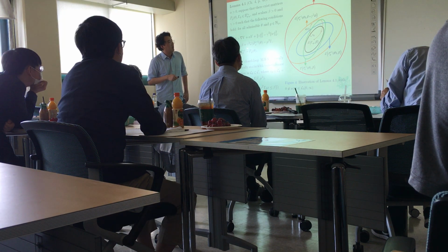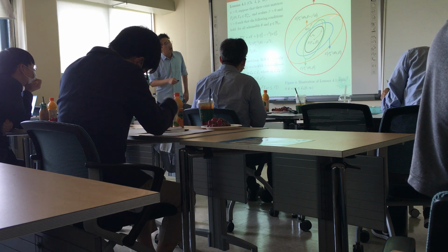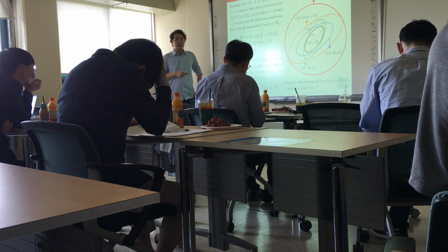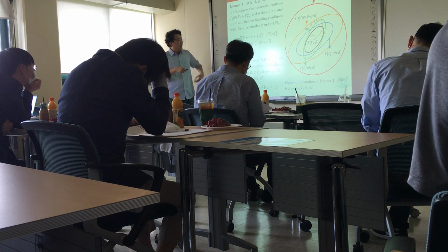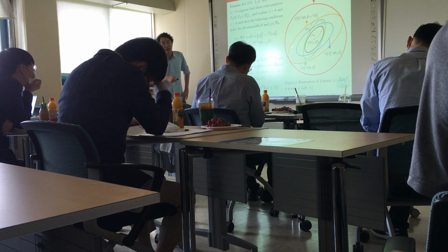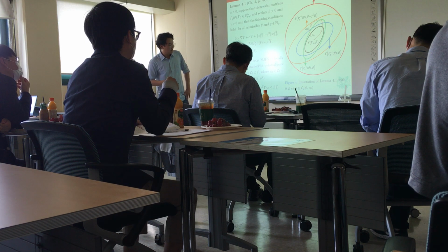The second inequality ensures that the origin ellipse lies inside the operating region, and the third inequality ensures that the local stability region belongs to the intersection of the green and blue ellipses.